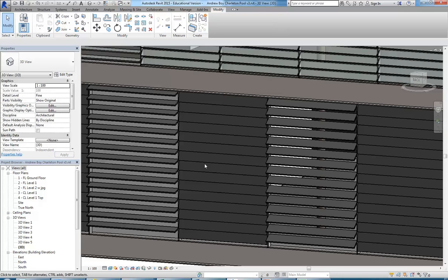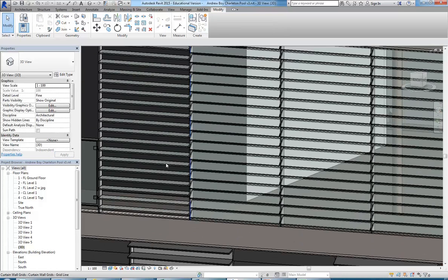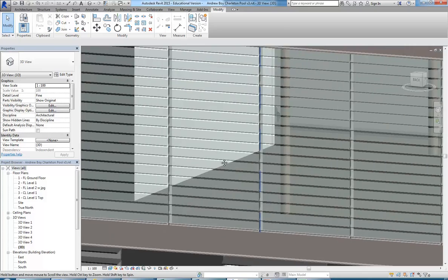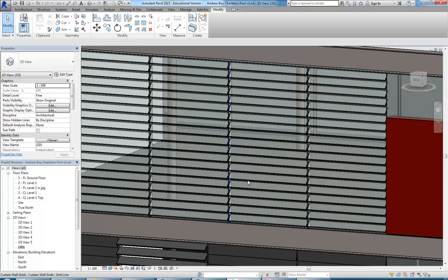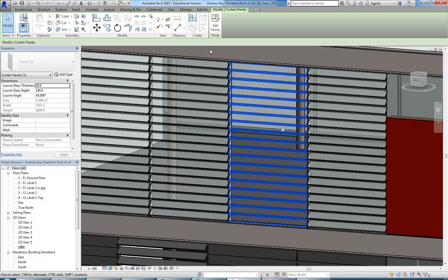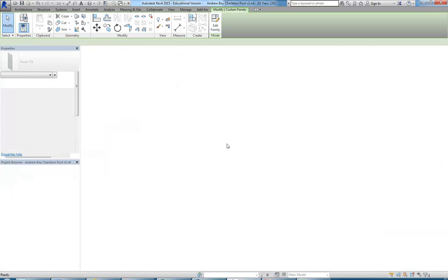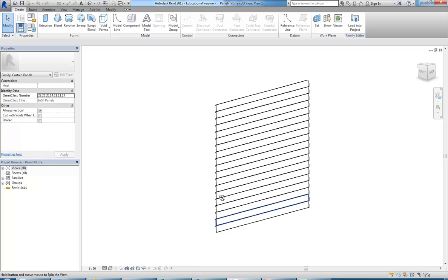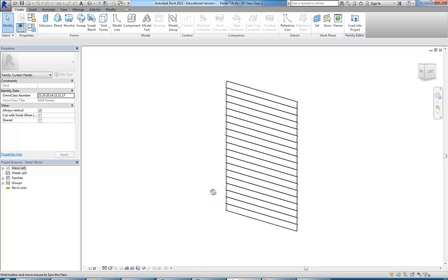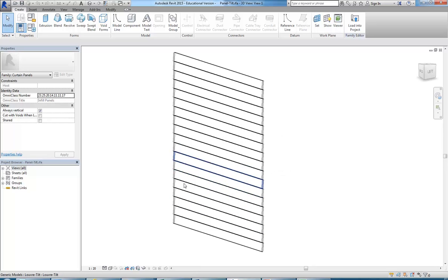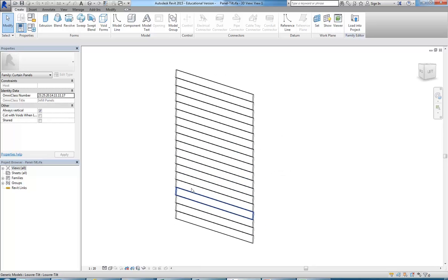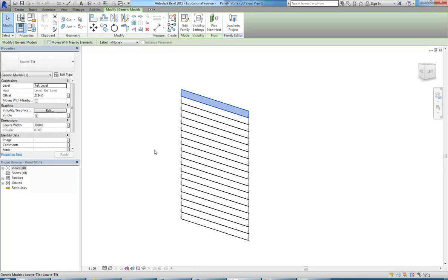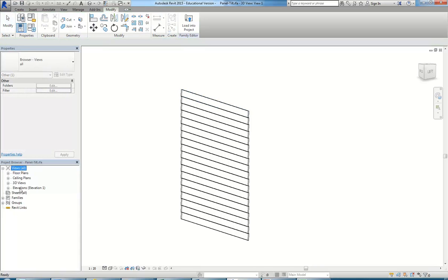And so I'll go and get the glass one the same way. So back to the file where I have all my families, project file, Tab, and I'll get one that's got a different angle actually, so I'm just going to select this one. And again, Edit Family to create a family file. And then it's good to look at how that's been created, because it's got the louvers there as a collection. And so the way I've done this family...